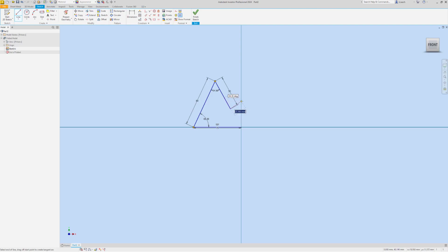I'm going to draw it out. What is that going to be? I'm looking. Does it say? I do not see where it says what that is. So, yeah, I don't see that. All right, so let's just draw it. I don't know, maybe 15 millimeters. I'm going to make sure it's perpendicular there. So 15 millimeters. Press the Enter button. And so that's kind of the outside shape. Then I'm going to right click, hit OK, and finish my sketch.